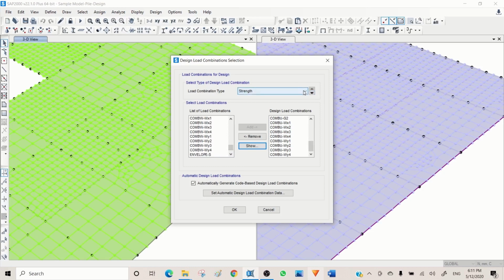So perfect. Coming to crack width. So here is checking the crack width. That means the service load. So we're coming here again and adding them all, and I check here if there is any S remaining. No, all good. And again, automatically generate code.